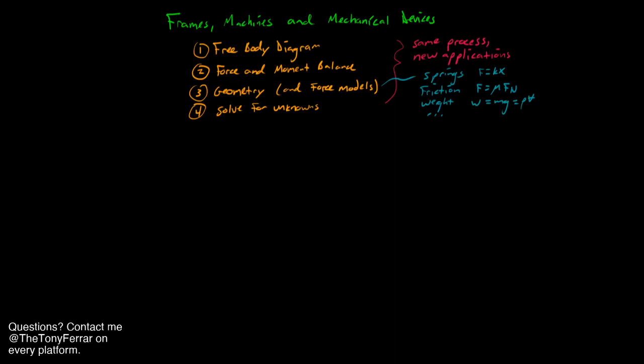As we explore the various applications of the concepts of statics class, I want you to keep in mind we are using the same process to look at new systems. So we're going to draw free body diagrams, do a force and moment balance, solve some geometry, add any force models that need to happen, things like springs or other types of friction, or weight or other physical phenomena, and then finally we solve for the unknowns. So, new applications, no new physics.